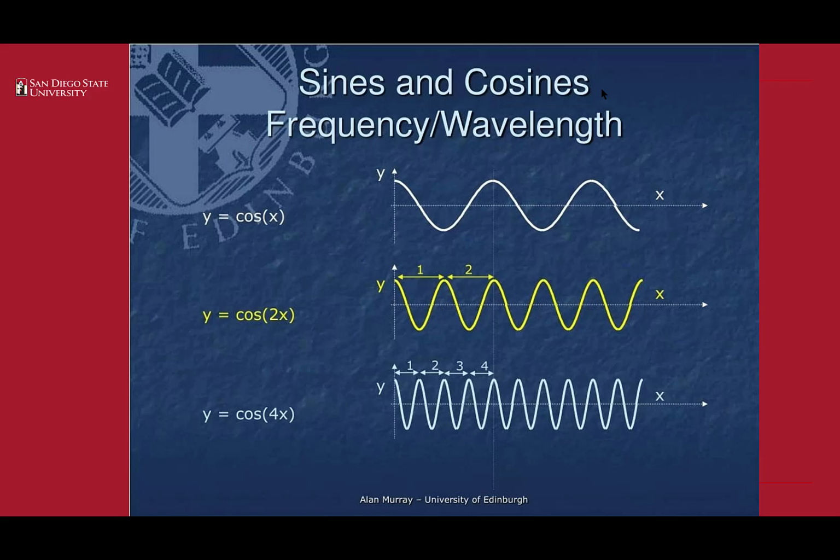And as you can see in the chart, the change is not the amplitude of the signal, but it's the period of the signal. Now, in this form, we have a smaller period. So the signal repeats itself again, but this time with a shorter period. So it repeats itself faster. And this also translates as this signal has a higher frequency, twice the frequency of the previous one.